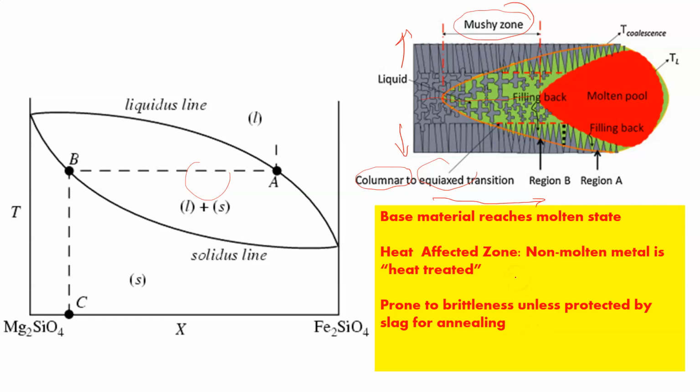What happens is the slag, which is essentially the impurities in the metal, that might have been absorbed in this metal, or may have come from some of the electrode, or just the surrounding air, if there wasn't a shield gas used, can actually start to form a crust on top of the metal. This slows down the cooling process and can actually help your grains. It can make the material less brittle and more ductile. So again, it helps with those columnar grains. If you have the slag on there and you leave it on the appropriate amount of time, you can have an annealing effect.